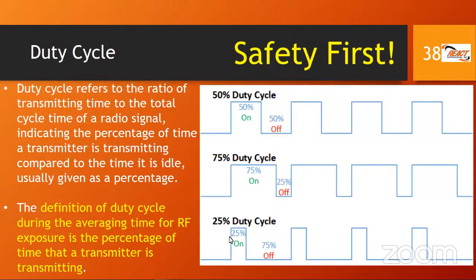But let's illustrate again. Let's say for 75% of that time I'm running, and then 25% of that time I'm not running. And 75% of that time I'm running. And it could be me running. It could be a motor that's running. It could be a blender. Some of us may have a cake mixer or a blender. We're trying to mix something, or an Osterizer, and we put it on and half an hour that thing is going, man. And then we wonder why that appliance didn't last any time. Because we have exceeded the duty cycle of it. It was not meant to be commercial. We're using a home blender. And that really wasn't meant to be on for 45 minutes at a time, right?